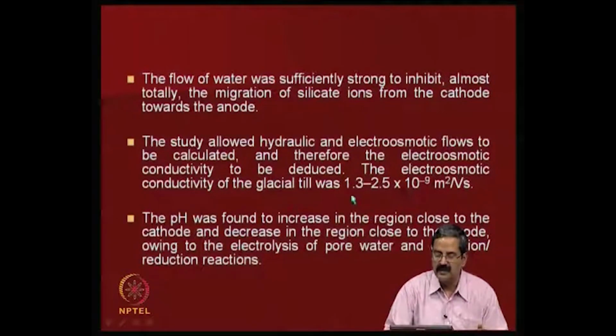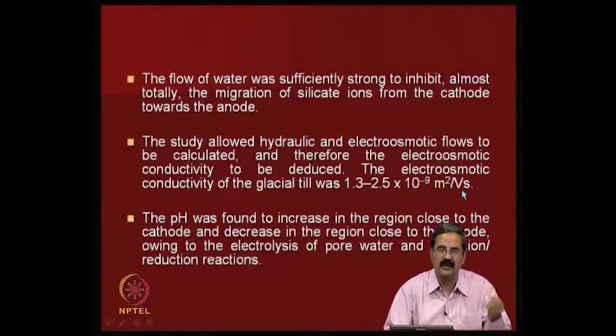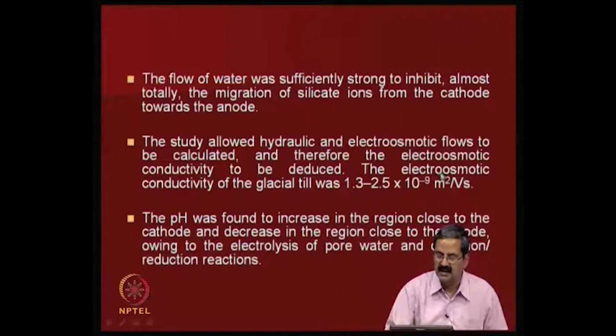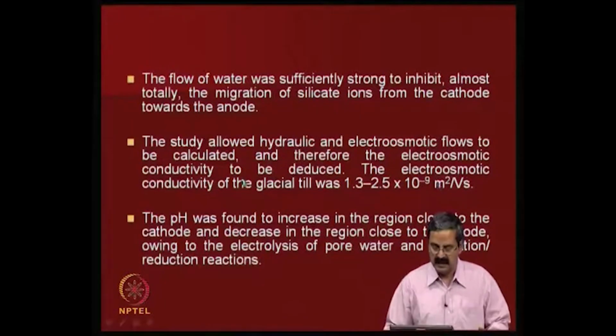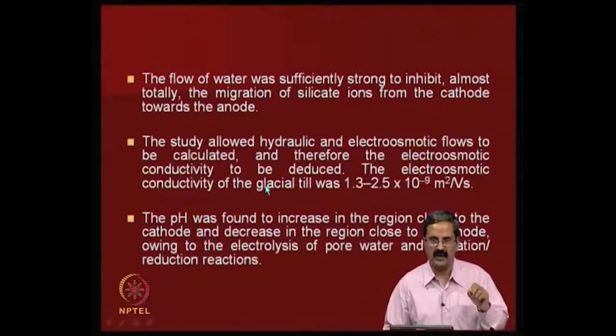We try to calculate the electro-osmotic conductivity of the material. It is 1.3 to 2.5 times 10 to the minus 9 meter square per volt second. So, per voltage difference, one can even say what the area is, and you have to compare the hydraulic conductivity and also the electro-osmotic conductivity. I mean, water removal is essentially what we are looking at.